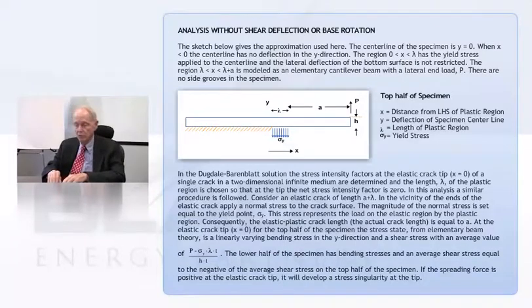Okay, so we need to talk about that, but before, what are you going to do about this crack? Because you've cut a slice. They use very thin saws to cut that groove in there to a depth A. But that's still not a crack. That's not good enough. The standards tell you what to do on this. I guess they've learned through hard experience that they give you a way to determine some cycles to apply before you start the test. And those cycles are enough to start a real crack from the tip, but not cause the whole thing to break through. So you have to go through this, and that makes the test more expensive, but you got to do it.